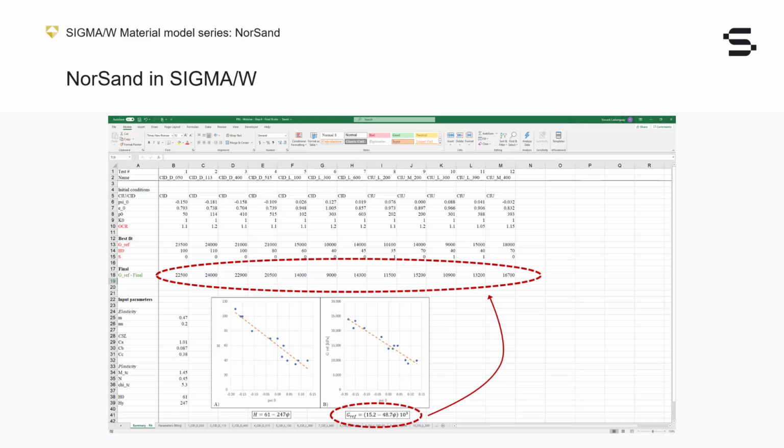for its initial parameters. A case could very well be made to also adopt a single value of OCR for all the tests, say 1.15 for example. The only parameter that would then be needed to be adjusted by the user would be the additional softening index S that still needs to be turned on manually for undrained loading of loose soils. Other than these caveats, the NorSand model we established provides all the necessary parameters to properly simulate the behavior of